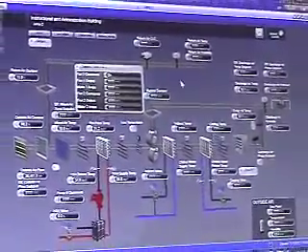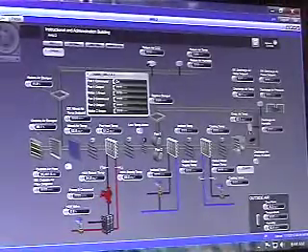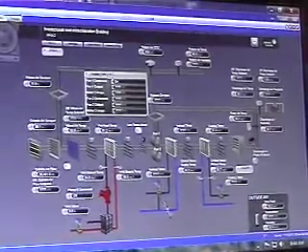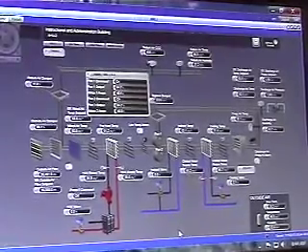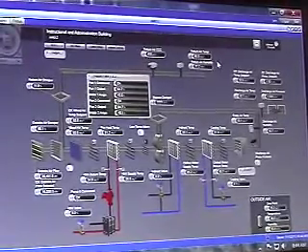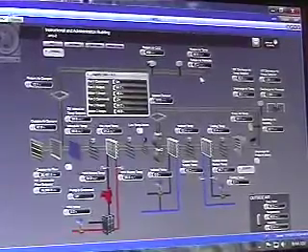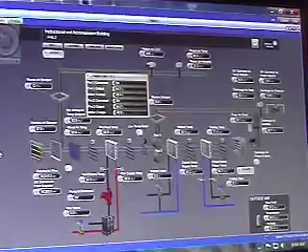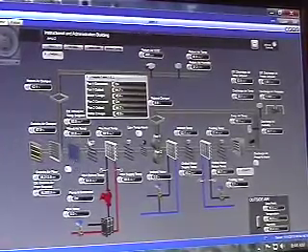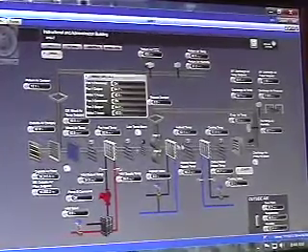So as we kind of mentioned before, there is quite a bit of stuff going on here, but there's a lot of good stuff to look at. So if we just look at the top, the way that this is set up is you have your return air coming in this way, goes down through your return air damper. You have your outside air here, and right here is where it's mixing in between, and it goes through all your coils.